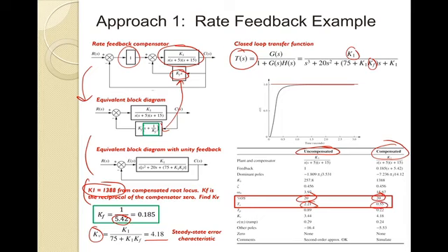Now, wait a minute. I thought my desired overshoot when I did this root locus design was 20%, but I would expect something like that, but I don't get it. It looks more like it's critically damped. So again, when I look at my dominant poles here for my uncompensated system, we can see they are complex conjugates, so we would expect overshoot here. And then for the compensated system, I have those poles here as well. So why does this closed loop character, did I get the wrong plot here, or what's going on?